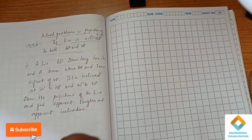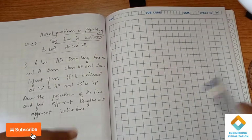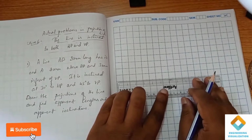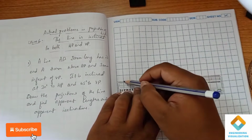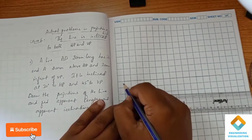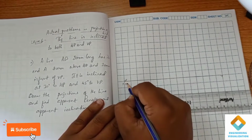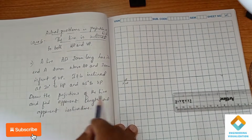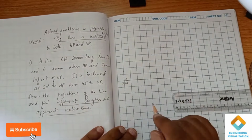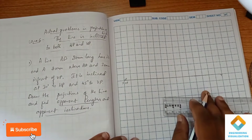First I am going to draw an XY line here. XY, VP, HP. In this problem we have to draw the projections of the line and find apparent lengths and apparent inclinations. As we have discussed, apparent lengths are nothing but the reduced lengths, which we have to find out.